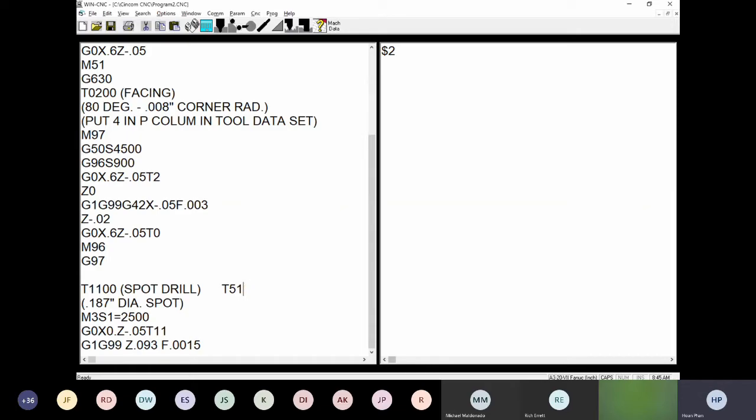So I always call the tool without the offset. In this case, we are worry-free about what tool we need to call with the offset and what tool we are allowed to call with the offset or not. So I always call it like that, and then whenever I'm positioning the tool, I will call the offset right here. The machine will work the same way. It will call the offset, read the offset and geometry all together in here. So I hope I explained your question.